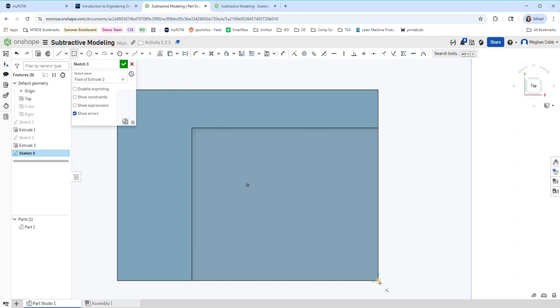So this one, again, just create your rectangle, and now we'll type in the dimensions. This one is going to be 2 for the bottom, and the height is going to be 1.5. Escape on your keyboard to get out of making rectangles, and I just want both of these to be outside of our shape here as per the dimensioning guidelines.